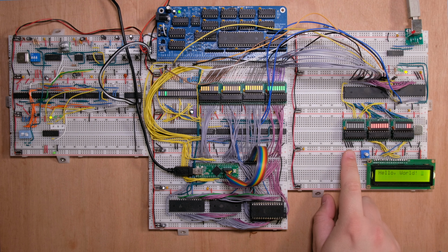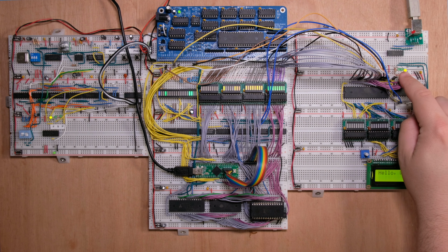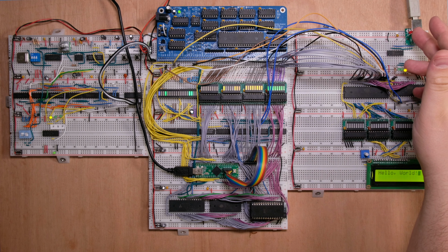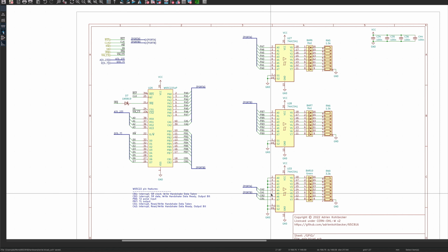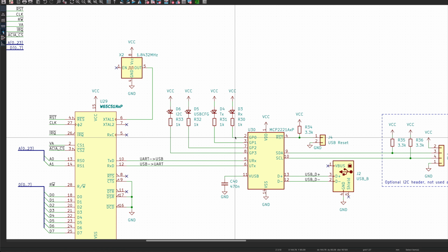And I have 4 LEDs left here on this 8-bit module that I want to use, and what I'm thinking is I'm going to move the status LEDs for the ACIA, which there are 4 LEDs, to this here. So I'm going to do that now. So now there's 4 signals here. We could take the LEDs for the serial communications, so those ones, and we use this display. So I guess we have to export the signals between the sheets. So let's label them.